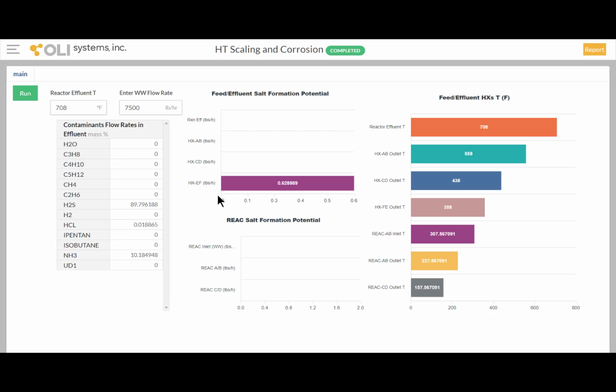And that's important because in the past, all we used to do is take the unit down, or if you had a bypass, maybe you could bypass, but not everybody has a bypass set of exchangers that are sitting idle until the other set fouls out. So in the past, we'd have to bring the unit down, open every shell, and clean them out. Some would be clean, some wouldn't. Put it back online, and it would take maybe 7 to 10 days of a turnaround, maybe 4 to 5 if your maintenance team was really well tuned to doing this kind of work.